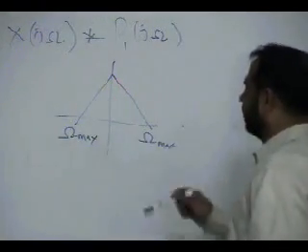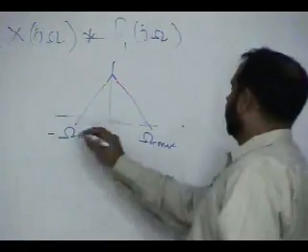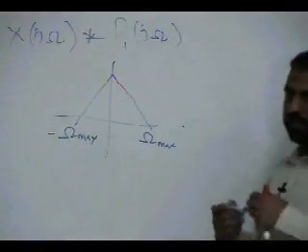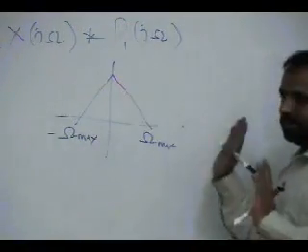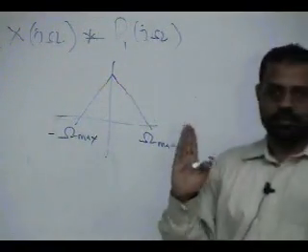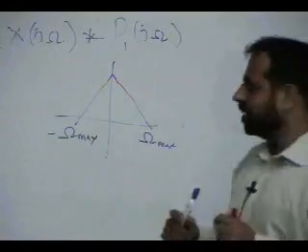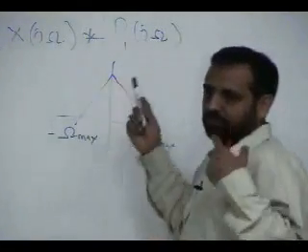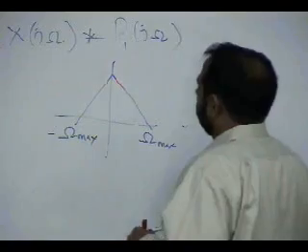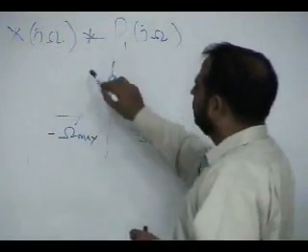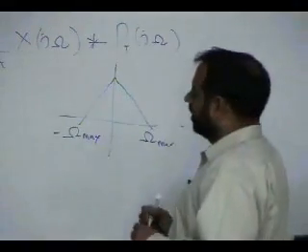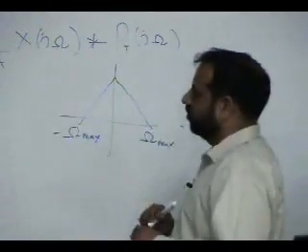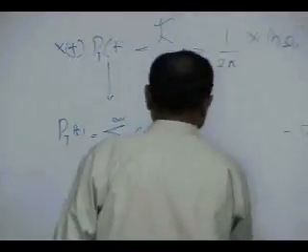So this is the band of the signal going from minus omega max to omega max. This is the Fourier transform of a signal. Shape is not important. We are only saying it is a band limited signal. If it is a real signal, then the magnitude will be symmetrically placed like this. So this is if we assume that X of j omega is this. Now what is the Fourier transform of this? It is a train of impulses.